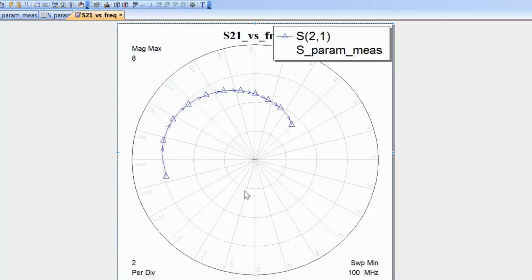We would have some kind of negative feedback, if anything. As we go up in frequency, the gain of the transistor diminishes in amplitude, and that is to be expected. If one looks at the model of a BJT, you can see that capacitances which are related to the transistor have a greater and greater effect, and hence they diminish the gain of the transistor.